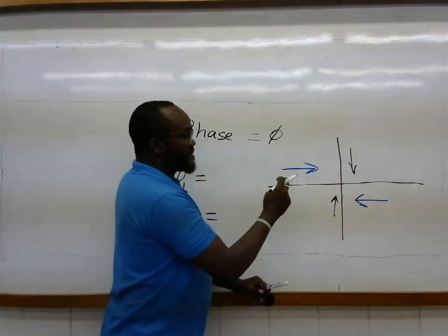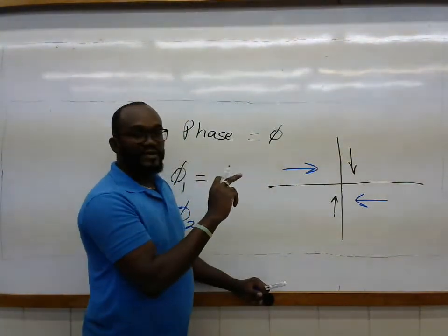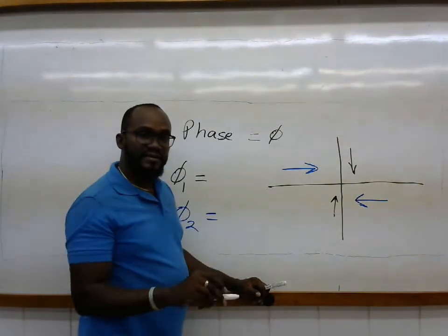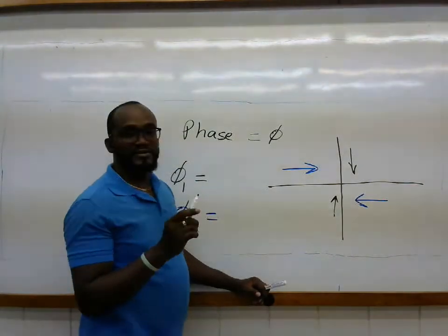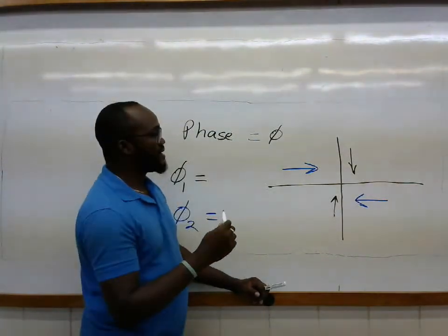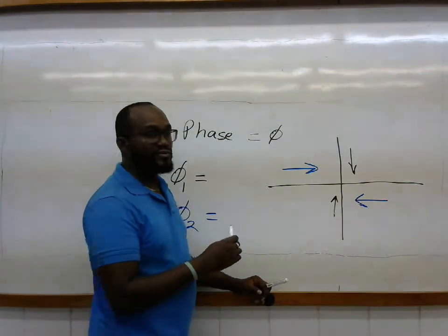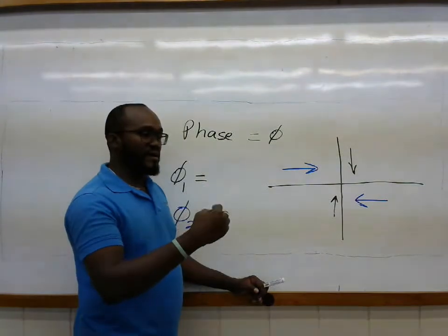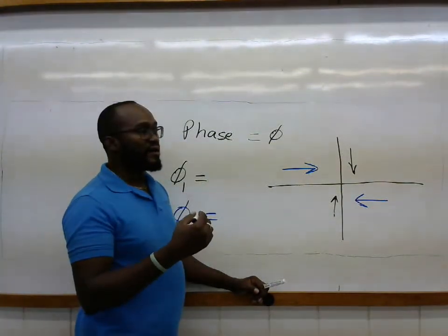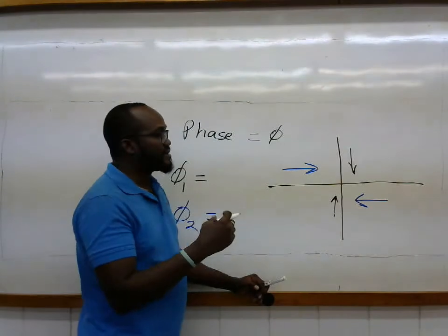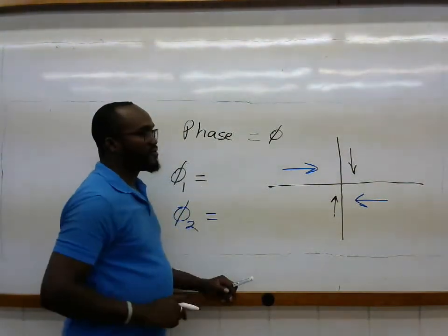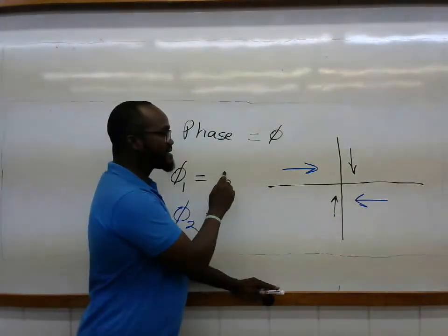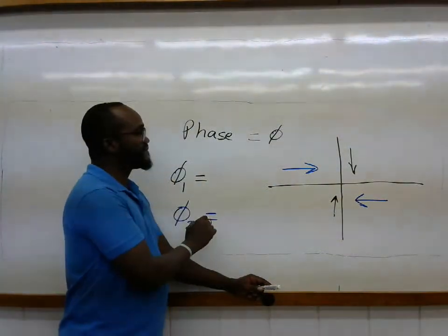Okay, now why is that important? Again, you recall the amber interval. There's a concept referred to as lost time. So there's time in the signal cycle that is underutilized or is not used at all due to a number of reasons. Right? So vehicles not being allowed to move, the reaction time for motorists once they get the green, that time that is lost in there, that is important, especially when it comes to how we actually set up the phases. So in principle, though, phases have a specific time and it's usually represented by phi.